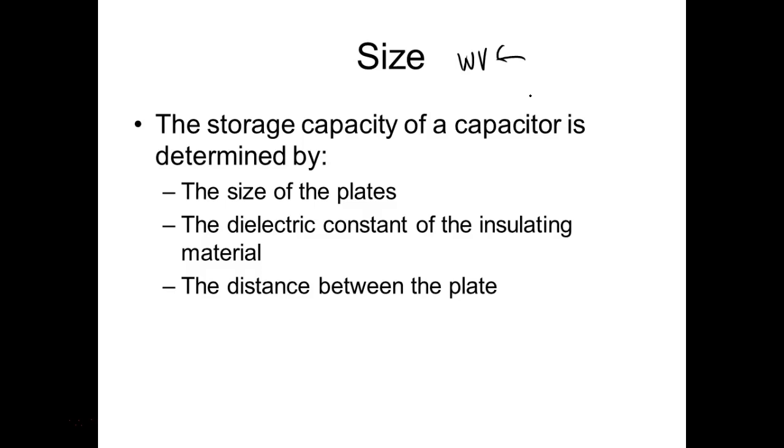With a little bitty one, if you use an ohmmeter and swap the leads around, it will show infinity in both directions. You might see your meter blink because they charge so fast. Your big ones, though, you can check those out. Or you can use a big resistor. If you have a little tiny one, just hook a resistor in series with it and charge it through that.